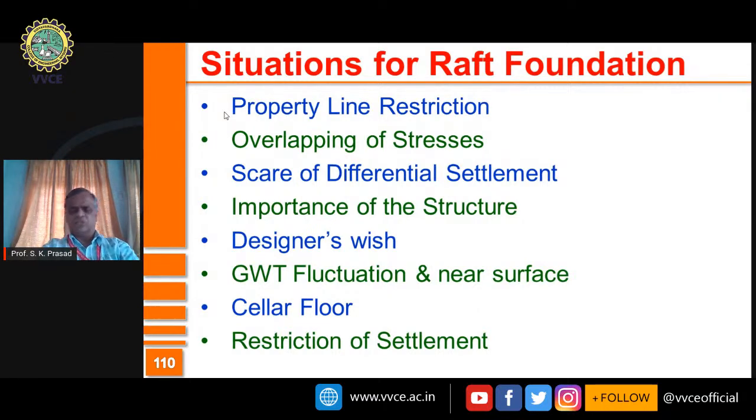So if such is the situation, maybe raft is one possible solution, because you seal the bottom. Even if the groundwater tries to rise, there is no scope, because the bottom is sealed. It can only penetrate through the sides, but not from the bottom. So whenever there is a fluctuation in groundwater table, many a times designer wishes to go for raft foundation.